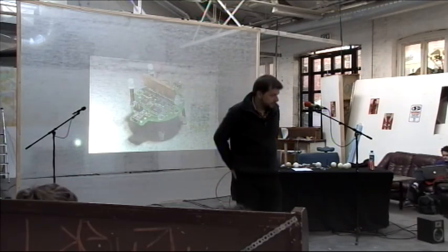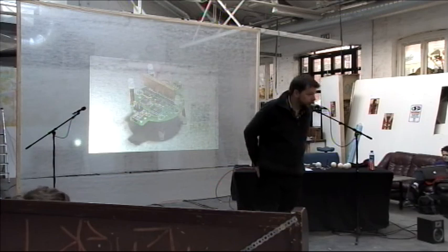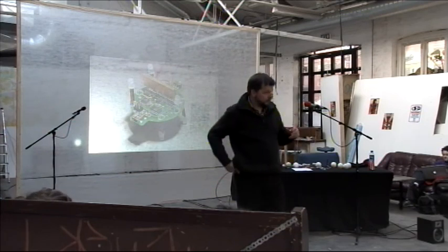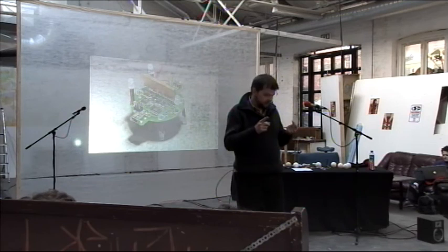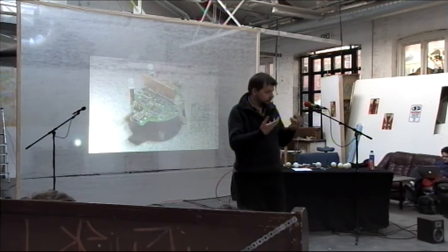Can you reprogram it over USB? Yes, that's the whole point. So you write code on Arduino, and you just plug it into USB and push upload, and then it uploads and you program. Not over the radio. Not over the radio, no. And that's because the radio has little delays. Whenever you send the bytes over to the Arduino, the CPU acknowledges that, okay, I got this string already into the flash memory, send the next part. And I think the delay is just too much, so it becomes not very fast.